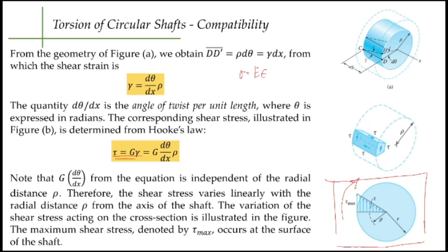And as you go inside, as you go deeper towards the center of the earth, no joke, towards the center of your material, shear stress decreases linearly. Okay? So that is the introduction part, wherein torsion is the introduction to problems wherein shear stress is not uniform, or stress is not uniform.